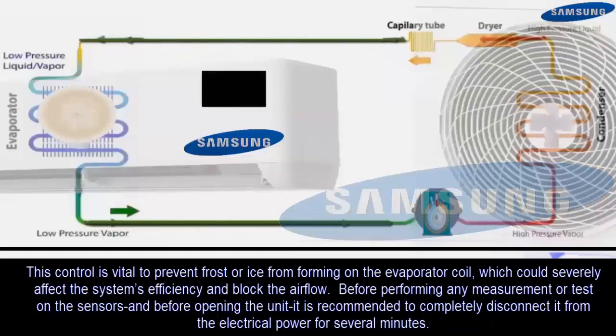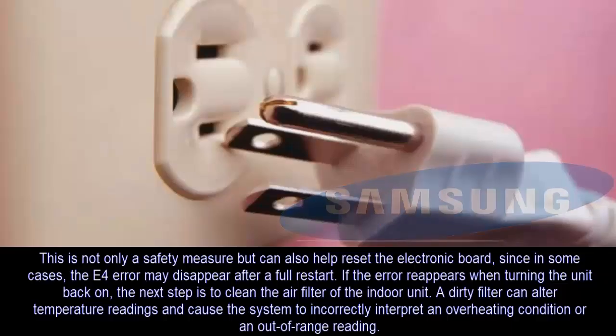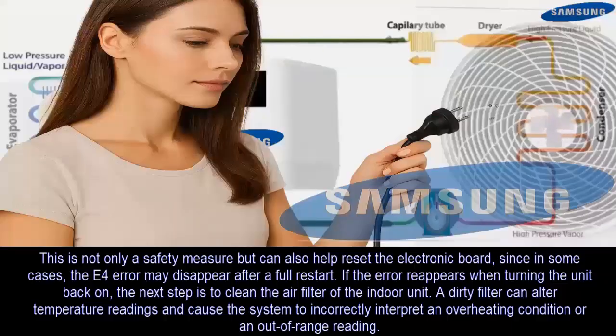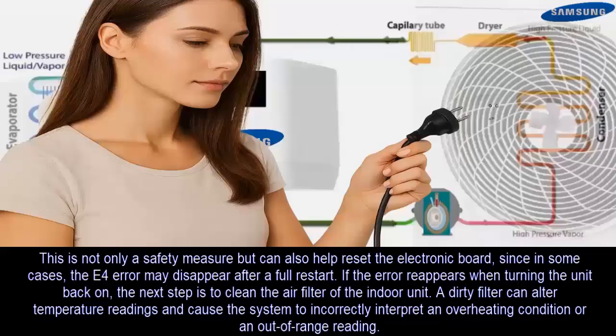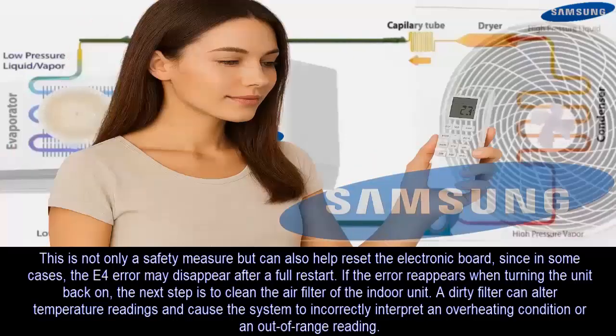Before performing any measurements or tests on the sensors and before opening the unit, it is recommended to disconnect it completely from the electrical power supply for several minutes. This is not only a safety measure, but can also help reset the electronic control board, since in some cases the E4 error may disappear after a full reset.